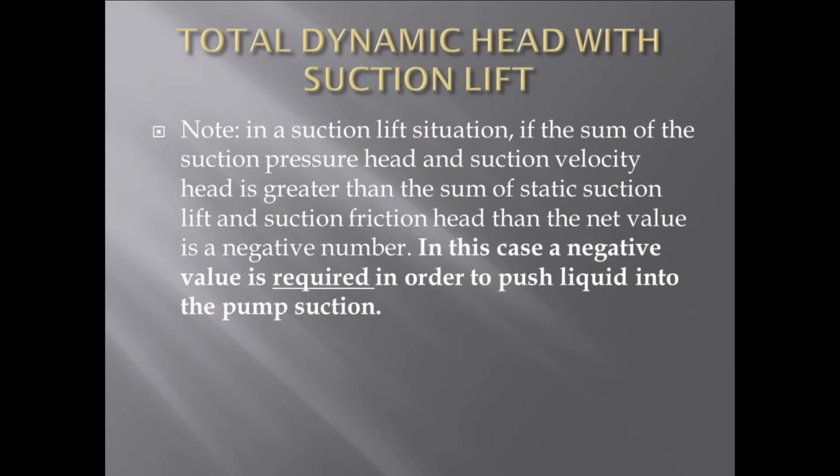In a suction lift situation, if the sum of the suction pressure head and suction velocity head is greater than the sum of the static suction lift and suction friction head, then the net value is a negative number. In this case, a negative value is required to push liquid into the pump suction.